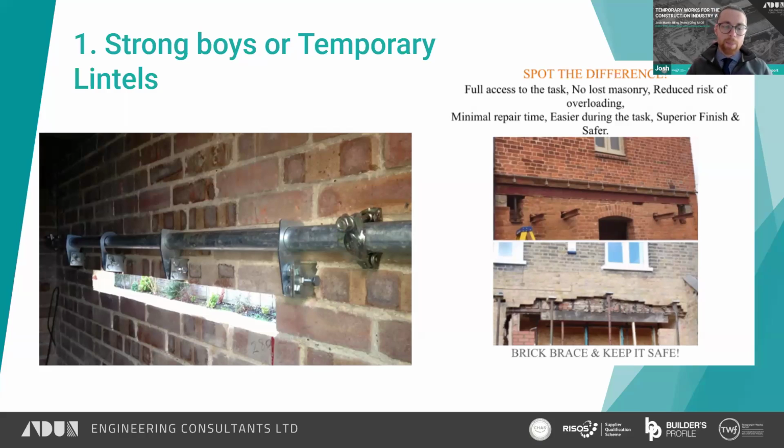And then there's 2 plates, which when you tighten those bolts on the side, start to open out. And as they open out, they put that bottom into compression. So they push the bricks out and create that big compression in the bottom there.